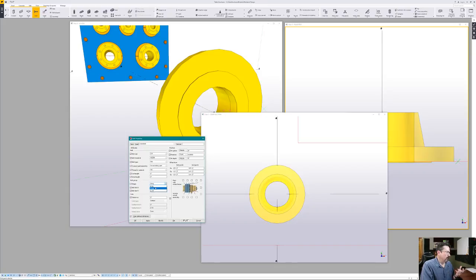up the shape. The shape in this particular case is going to be a circle, because we are drawing these in a circle. So we set up the circle, and it's going to ask the two pieces of information that we already know, which is what is the number of bolts. In our case, it's 8. And what is the diameter of the bolt circle. In our case, it's 7.5 inches. Now we can hit apply and actually go and put the bolts on.